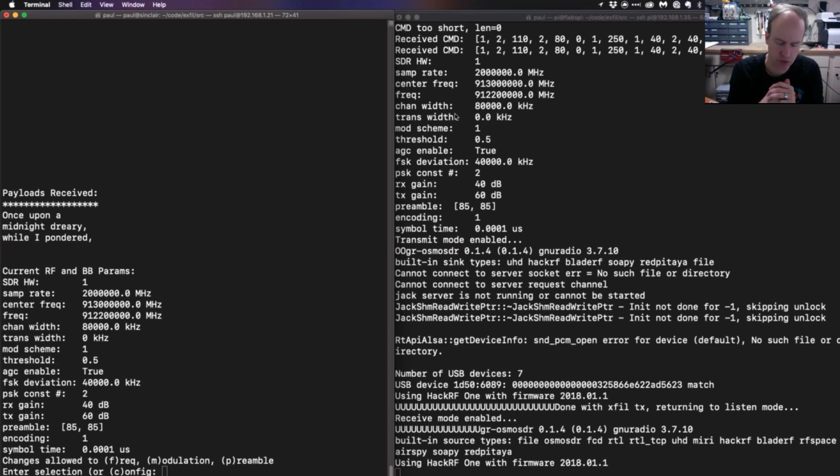If you have an idea of where it might be, either because you found it or because you suspect a particular type of hardware is in play, then it's a matter of setting an SDR to a bandwidth wide enough, a sample rate large enough, to capture enough spectrum that you can see all of the hops inside of that.